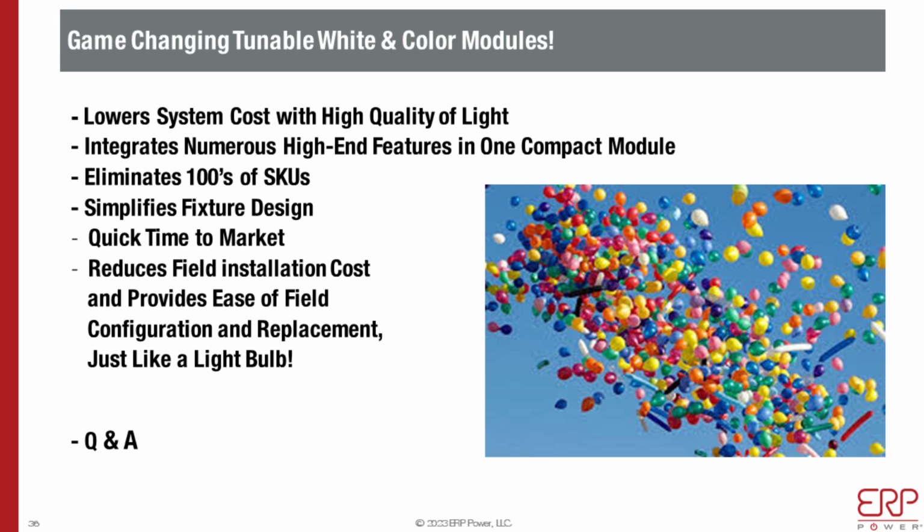Okay, so internally we set it, obviously we want to protect the LEDs, we don't want to go over like 85C to 90C, so that is what we trip it at. So as soon as the TS gets around, let's say, 90C, we're going to trip it. But in all practical applications, as I said before, you've got to look at keeping the TC of your module sub 75C, and you'd be fine. But internally, that's how we trip it.